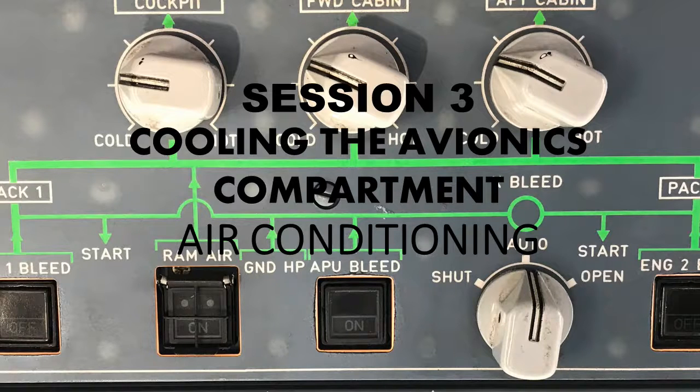Okay, and then we have an operation of the skin heat exchanger. The three pressure switches I mentioned earlier, remember I said these are pressure switches detecting a decreasing pressure or airflow. So with the vent blower fault, the two pressure switches are involved, detecting and sending that information to the ventilation computer.